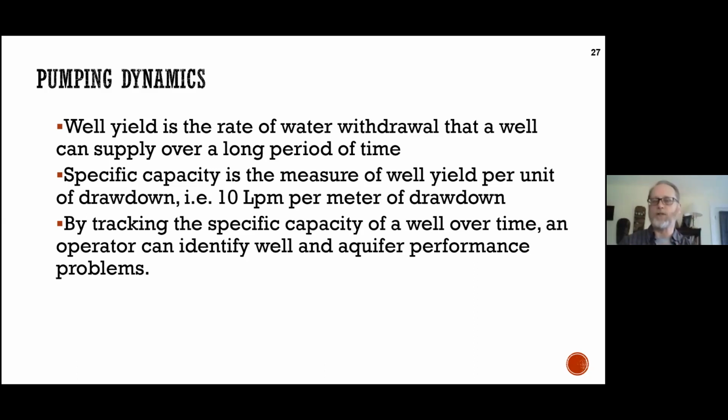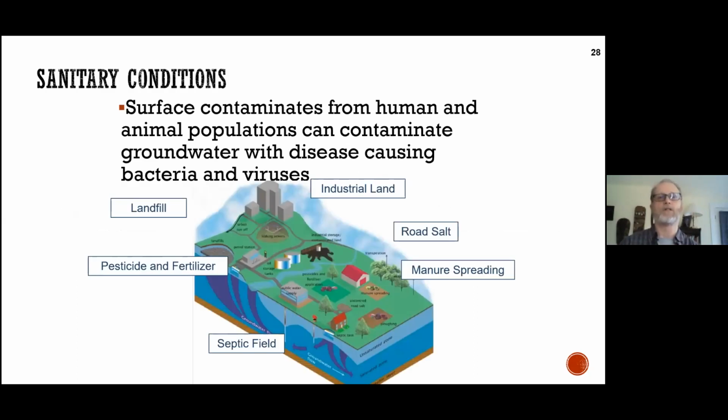first of all, is the aquifer still capable of sustaining the well based on what the customer needs, or customers, and what is the effect of time on our maintenance programs. Do we have to replace the well? Do we have to clean the screen at the bottom of the well casing? What do we need to do? And that we basically use the numbers through the pumping rates in terms of yield and capacity, specific capacity, to determine how our maintenance works.